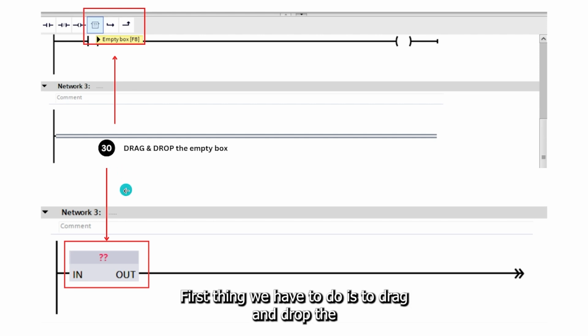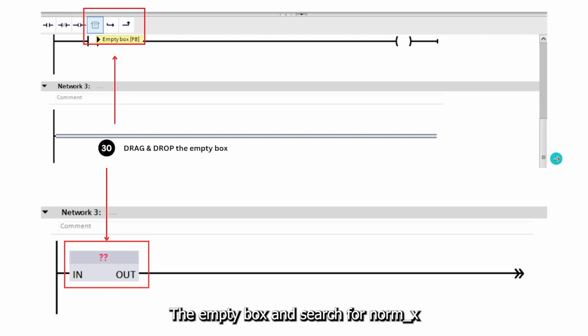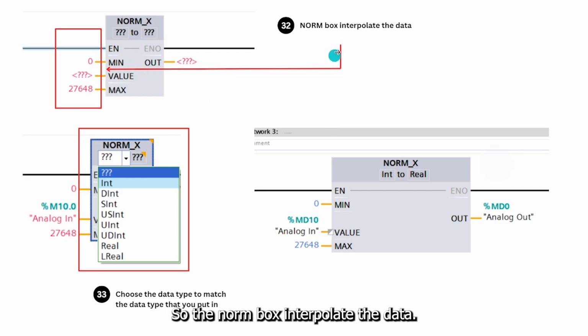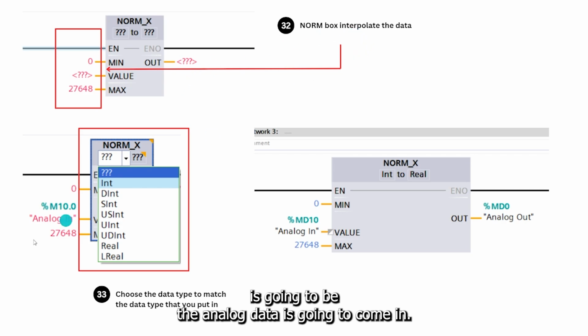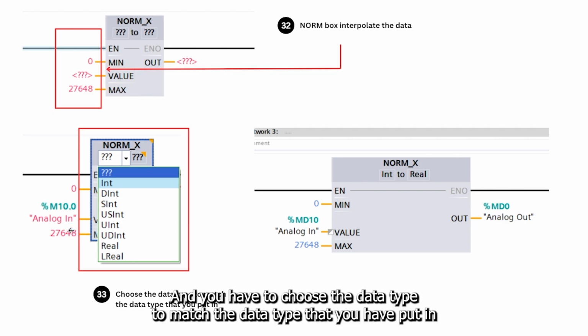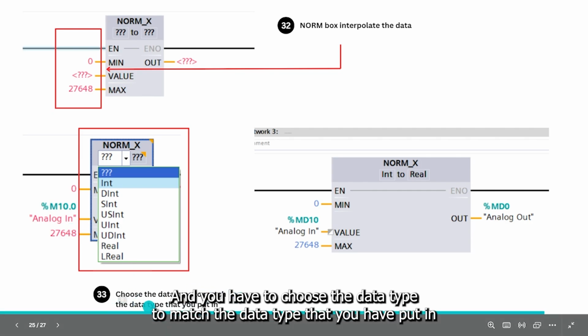First thing we have to do is to drag and drop the empty box and search for NORM_X by typing norm in the empty box. So the NORM box interpolates the data. The data to be interpolated is the analog data, which is going to come in as a word, 16 bits. We have to interpolate it into a range of 0 to 27,648. And you have to choose the data type to match the data type that you put in.